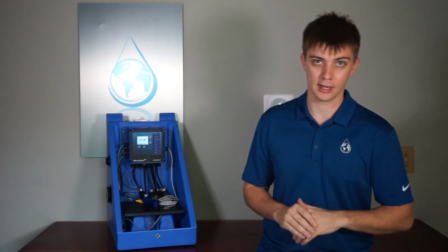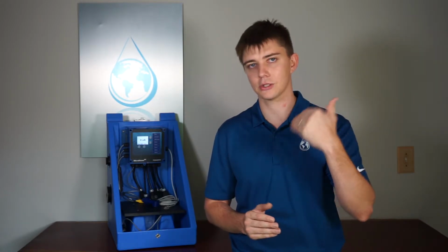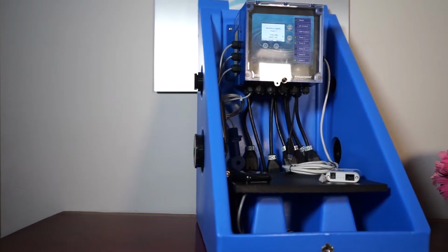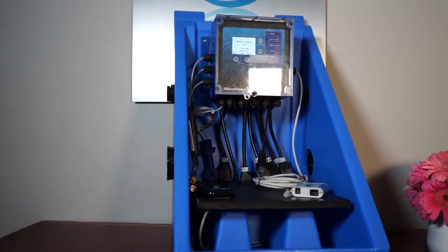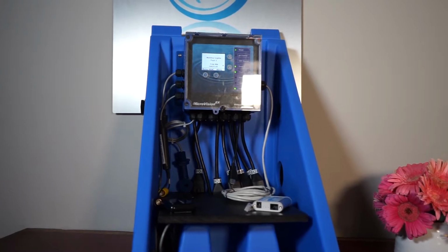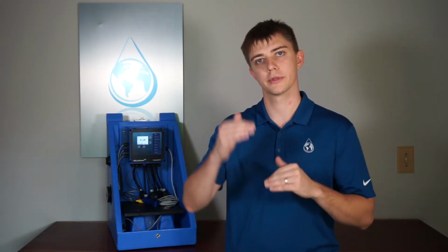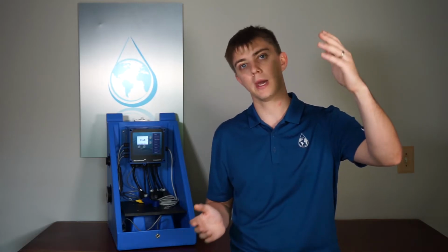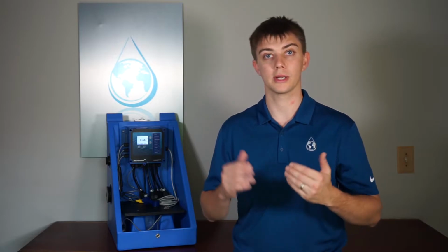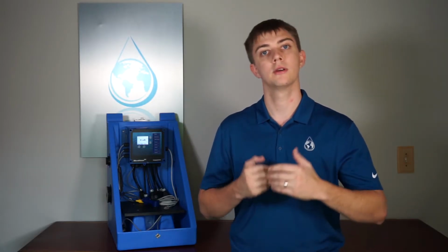So make sure you define a limit timer so that the pump will only turn on for an hour and a half, 2 hours, however long you think the maximum time it should ever organically see in the process. Once it exceeds that, it turns the pump off. Make sure you select turn relay off once your limit timer's hit. Then you can also define high and low alarms. So if your value is outside of those bounds, the controller goes into alarm as well. On an online controller, when it's out of those bounds, it could email you, notifying you that that parameter is out of range, and you can implement corrective measures.